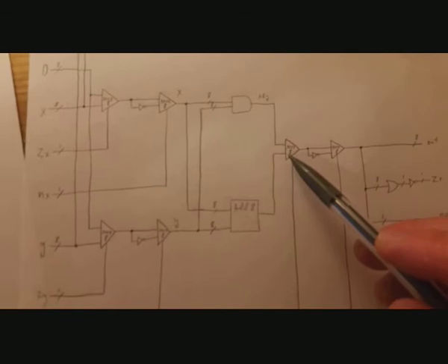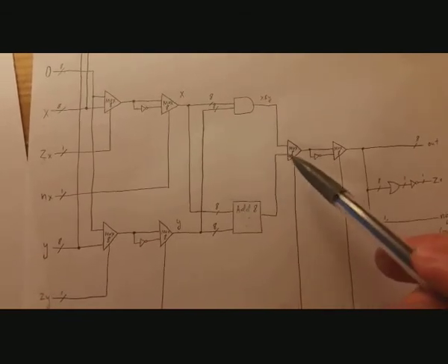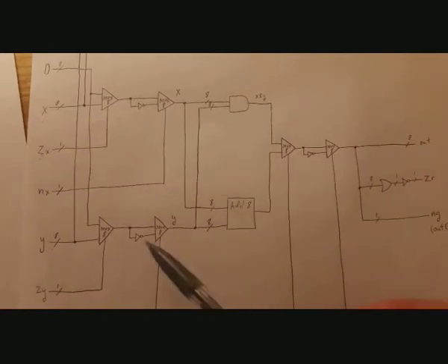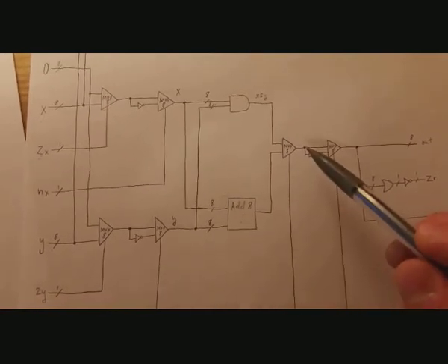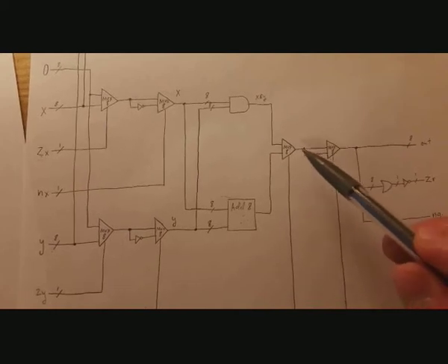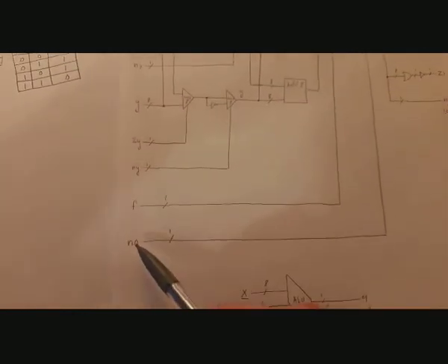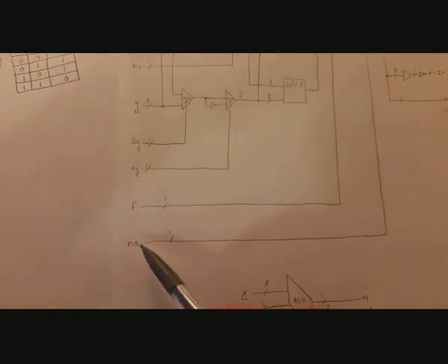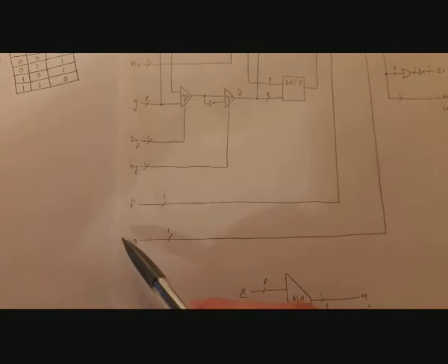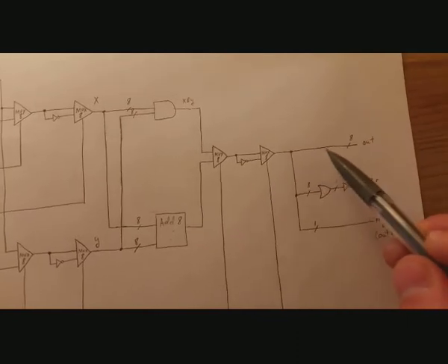So that's a multiplexer that chooses which of these we want. Once again, we do the same kind of trick where we split that value and send it as it is, and then send it with its bits flipped into a multiplexer. And this is NO. This basically flips the bits of the output. So that's just sent out, and that's the output.